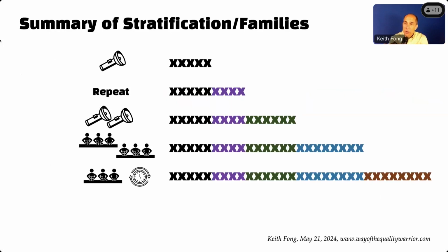So that's the idea of stratification: we want to get the smallest set of potential causes. We start with the smallest family because the fewer causes we have to deal with, the faster we solve the problem. We also want to do it in a structured way so that we're not saying, oh, I want to compare between two lines, when maybe just turning the same part on and off, you get the full range of variation.